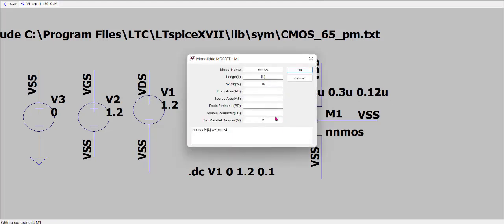Here you can see that in the MOSFET I have just put a variable in place of length, and I have declared a width of the MOSFET. So the MOSFET current equation has an aspect ratio, right? W by L. Unless you specify an aspect ratio for your MOSFET, it will not work. So W and L values you have to specify. Okay, so here I have put a variable L.